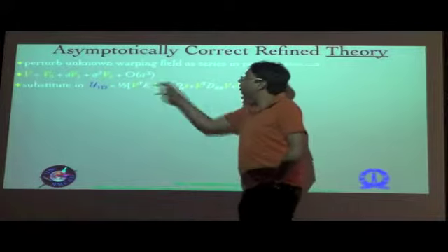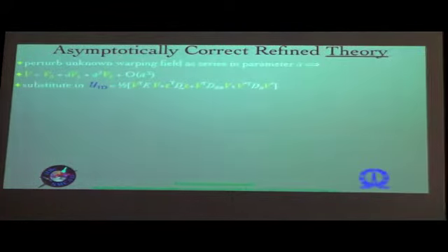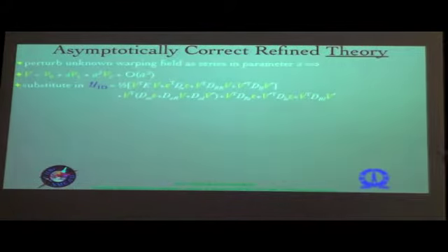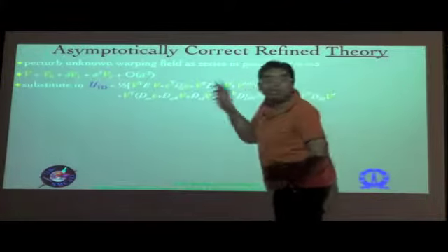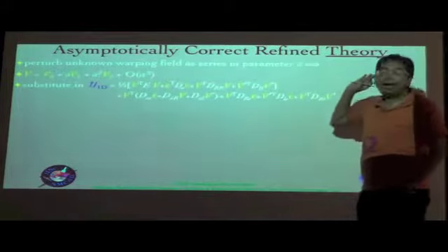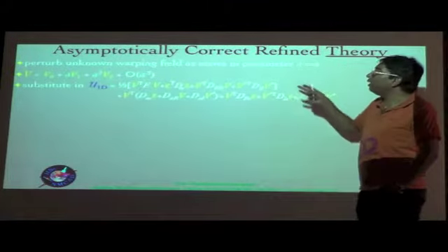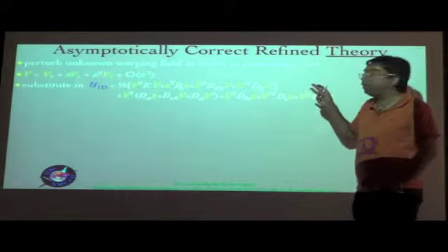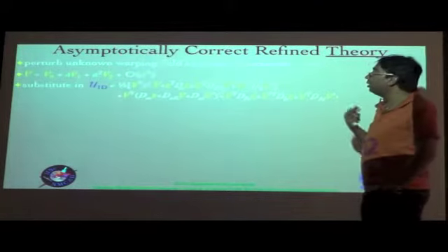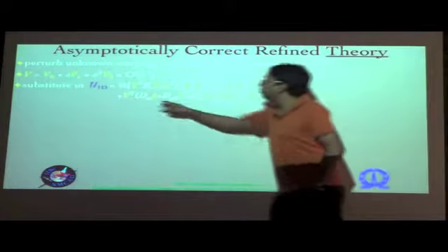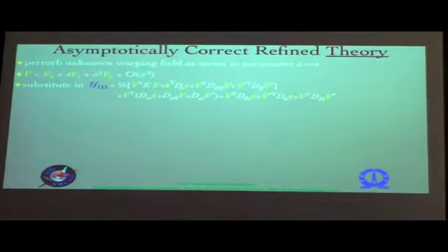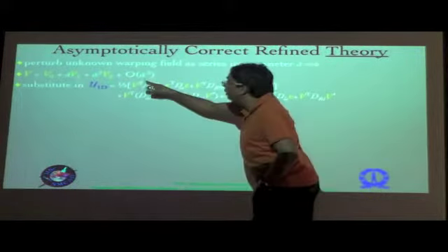So we substitute into the, sorry, this is not the full expression for U1D. So these are all the terms of U1D. You remember we derived that earlier today. So basically, this is the exact expression for the 1D strain energy density, the energy per unit length of the beam, obtained by integrating the U3D over the cross section, right? And of course, the cross sectional integrations are all contained within these D matrices and one of the E matrix.